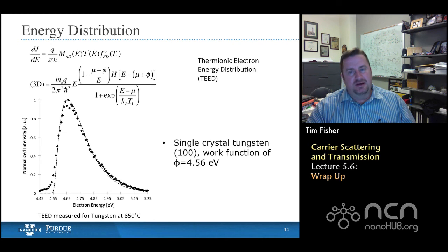And thermionic electron sources are useful in general for electron sources on, for example, scanning electron microscopes, but also thermionic emission can be used in energy conversion processes. It's also important just for kind of plain old electronic transport and understanding how current can leak. If I have a device that's getting too hot, how current can leak over a solid state barrier, in which case it's not vacuum emission, but it would be an internal solid state thermionic event.